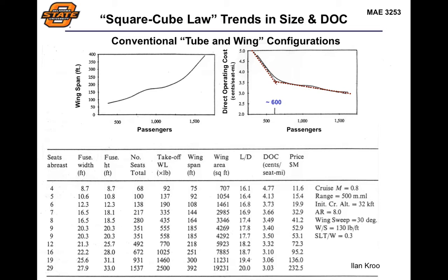That cylinder is going to relate directly to the size of the wingspan on the aircraft. And now we have to start thinking about this from a logistical standpoint. Why don't we want to build a 1,000 passenger aircraft, for example? So in this case, when you start looking at the size, there has to be an upper limit because you can't always fit this aircraft into an airport. There's not going to be a gate that's going to be able to fit this larger size.